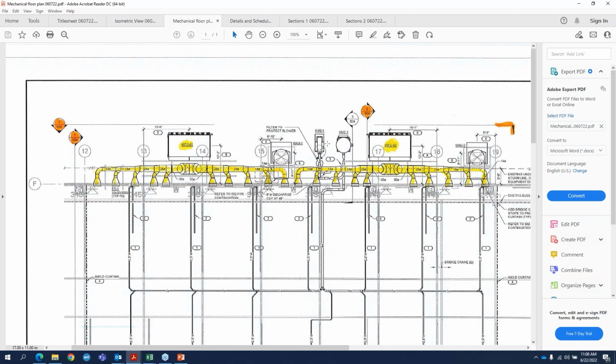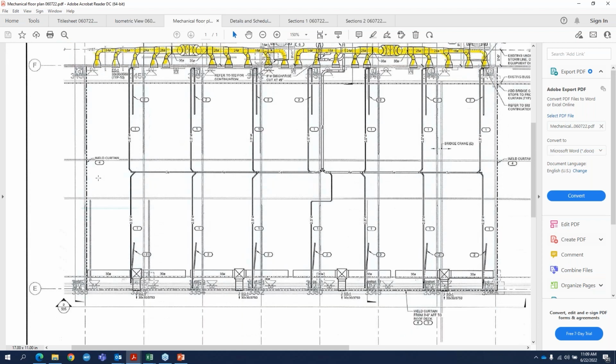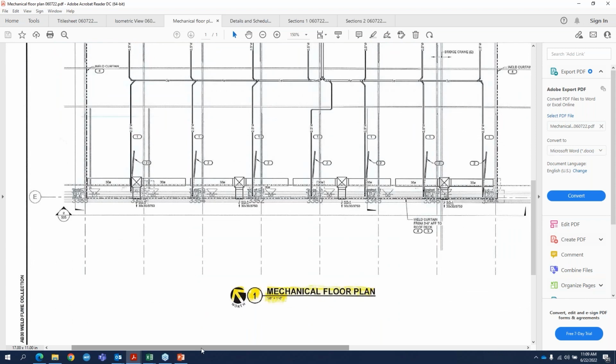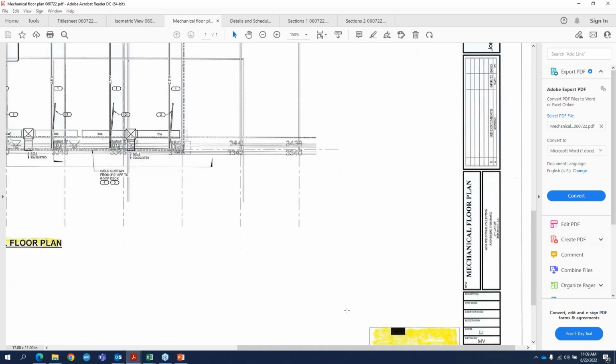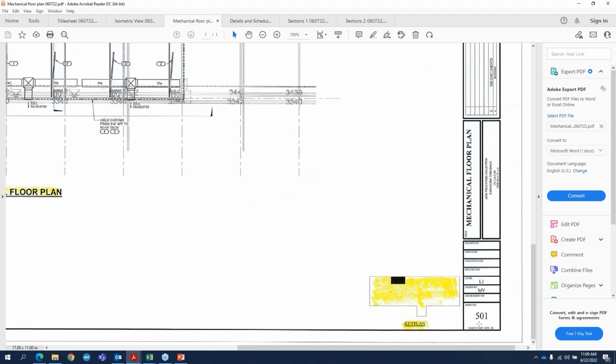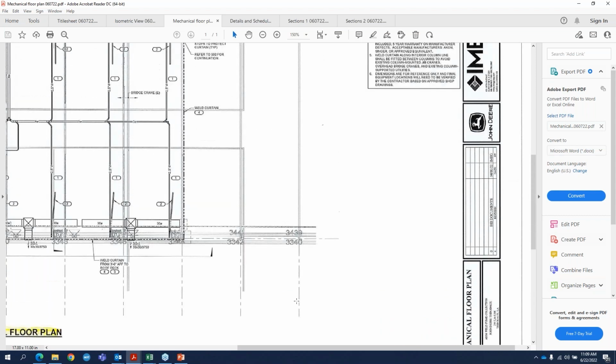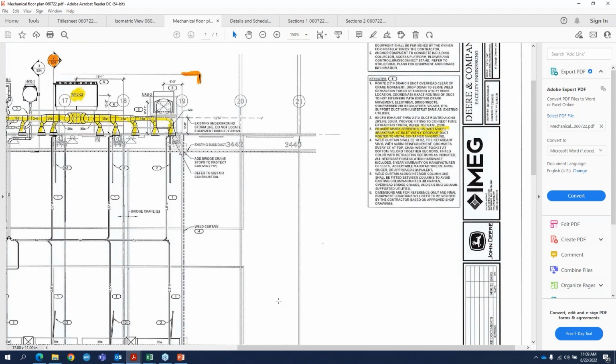Really, this one is an elevation because we're outside. We're not really cutting a section, but I'm going to show that to you. But that section 1 is located on sheet number 505. And if you go to your title box down at the bottom, there's your drawing number. So we want to find 505. And that will have that elevation on it.